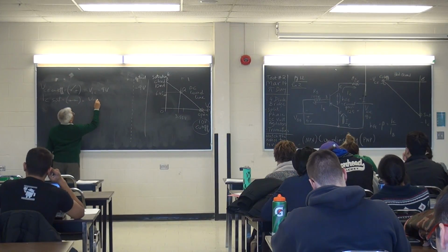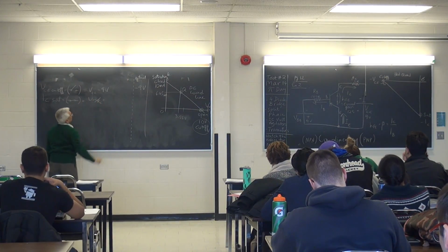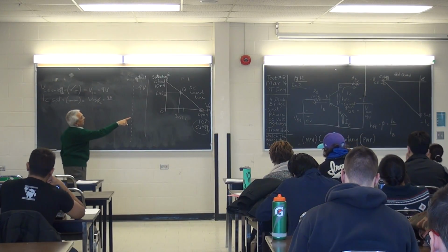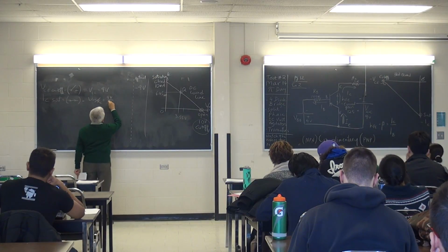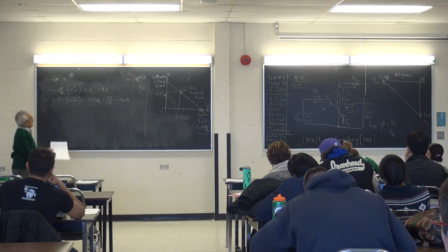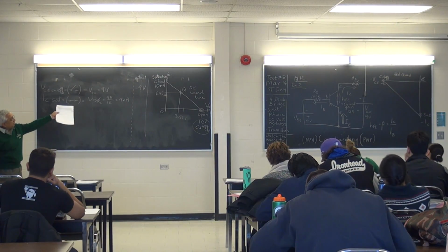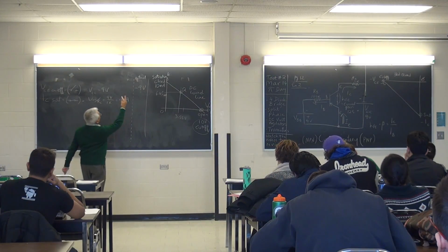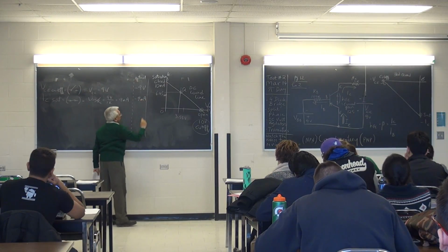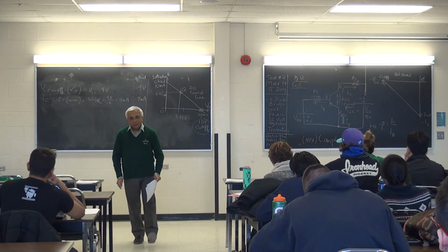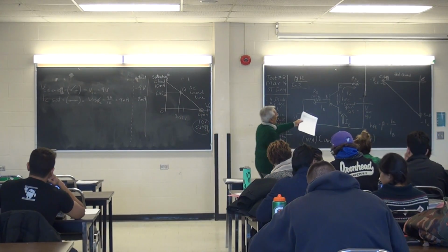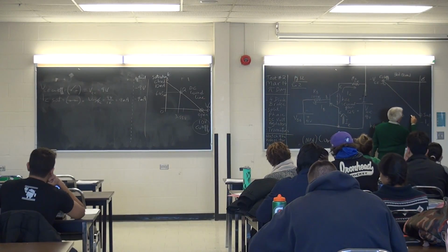So that's VCC over RC, which is 9 volts divided by 1K. How much? 9 milliamps. Because the direction of my current is opposite to the NPN, I indicate the actual value after the dotted line, negative 9 milliamps. Okay? So that's IC sat. Let me show the value of negative 9 milliamps on the graph right here.